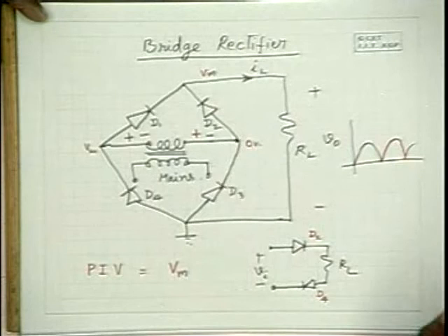Any questions so far? Any other advantage? This is one advantage. The other point is that two of the diodes are in series, and rather it is a disadvantage. So two diode forward potentials get subtracted from the waveform. Okay, so that's all. There is no other advantage. The load or the power dissipation do not get changed.